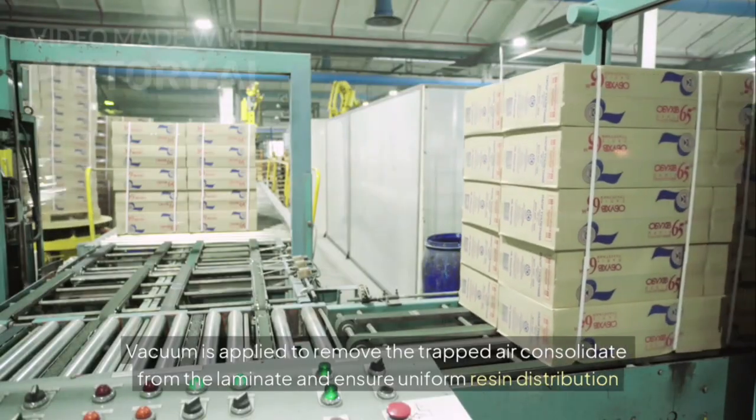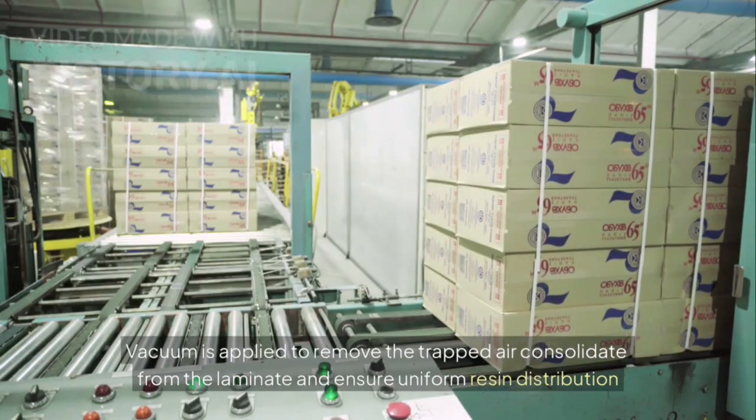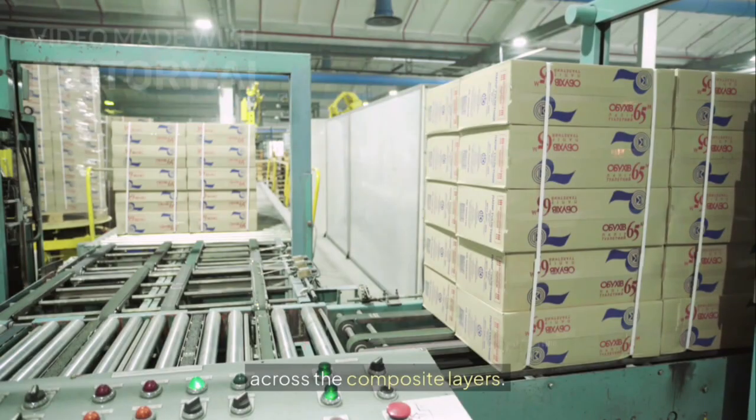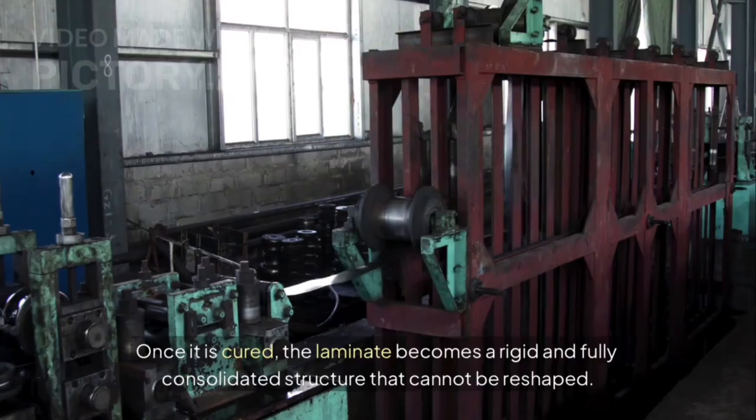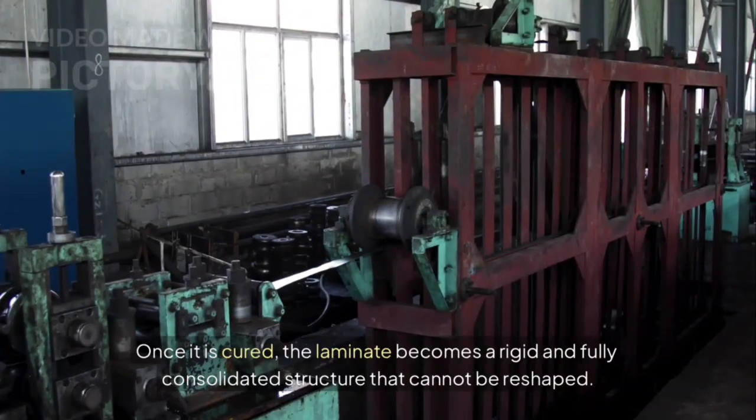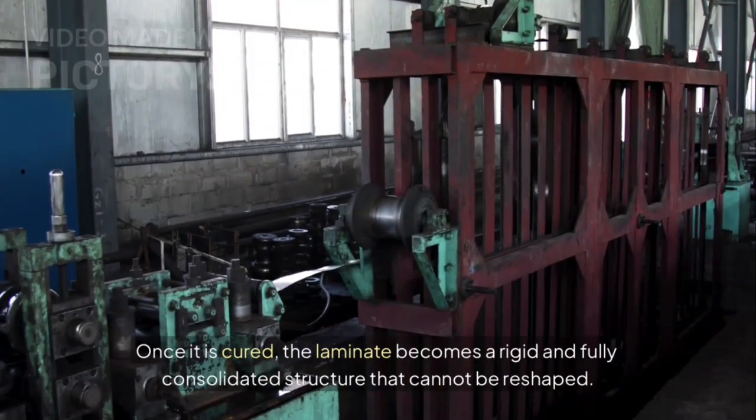Vacuum is applied to remove the trapped air, consolidate the laminate and ensure uniform resin distribution across the composite layers. The last step for the main process is autoclave curing. Once it is cured, the laminate becomes a rigid and fully consolidated structure that cannot be reshaped.